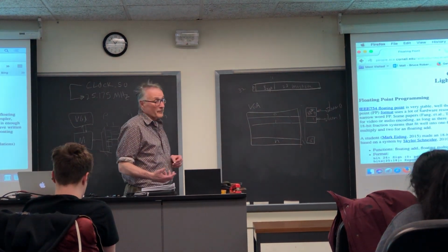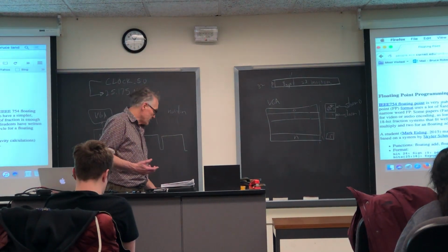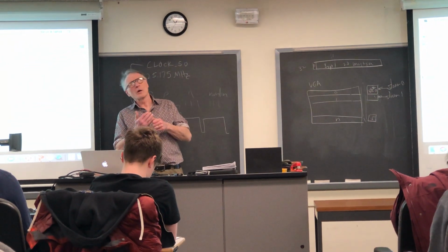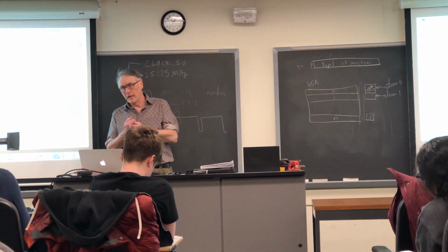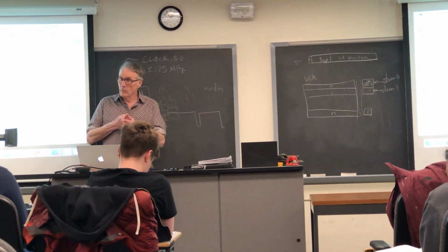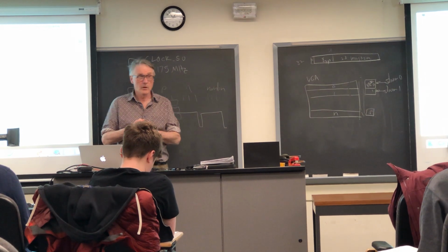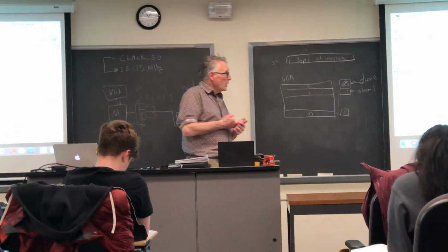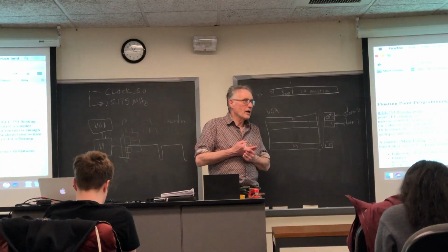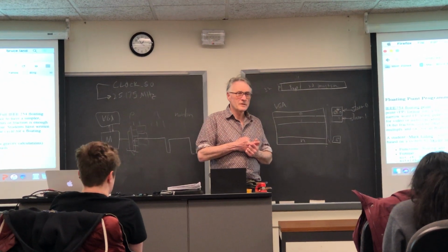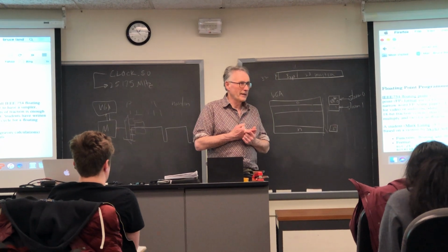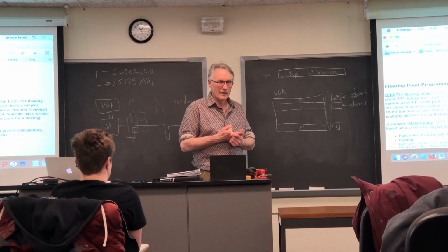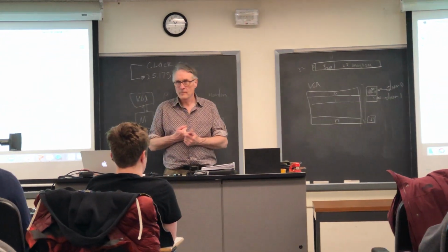Full IEEE floating point not only has this format, it has special values for positive infinity, negative infinity, not a number, illegal number, and a few other items. All in all, it requires a couple of thousand ALMs to implement a floating point add in IEEE format. It's too big to be handy.